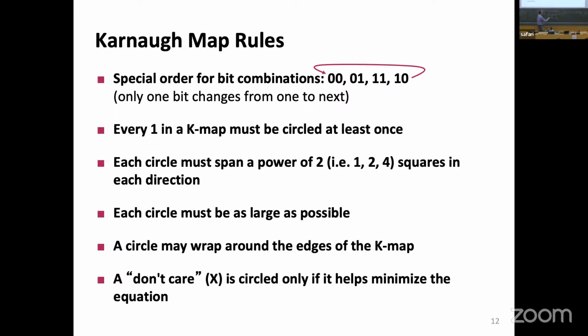Now, I've covered everything. I can write this, but it will be redundant, because this one already covers every possible case where the output is a 1. So if I cover this as well, like you're asking, I'm adding another literal, but I'm not changing the result. It's a redundant addition. But what you ask is correct. You could have also done this. Instead of adding that guy, AB, we could have added this guy, which is A, not C.